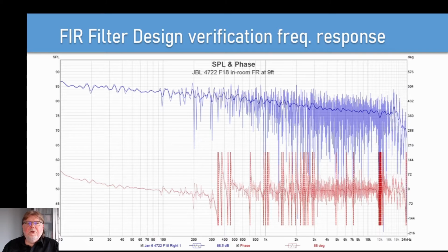Here we can see the results of a room correction transfer function with the right amount of psychoacoustic filtering and frequency-dependent windowing. Just standing a mic up at the listening position and using REW's default window time of 500 milliseconds is letting in all of the frequencies from 20 Hz to 20 kHz with the same window length. In this case, we're just looking at the right channel.